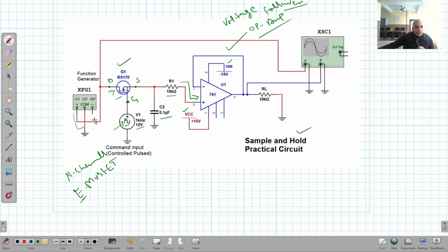So whatever input signal is applied here, this signal will go to this MOSFET, and when this gate is open and this MOSFET is behaving like a closed switch, then that time this entire signal will go to the capacitor, and the capacitor will start charging to that voltage, right? It will continue charging, and then after, you can see here the negative cycle, or zero potential, will reach the gate, right? If I take this reference as 0 and this as plus, then the gate will become zero potential. Now in this case, as I said earlier, this MOSFET will behave like an open switch.